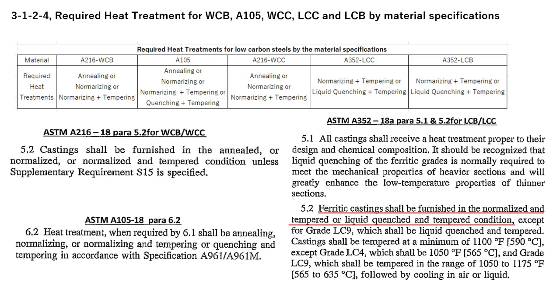Normalizing and liquid quenching make the material structure small, a fine structure. So related to toughness, the property is very effectively improved by normalizing and liquid quenching.